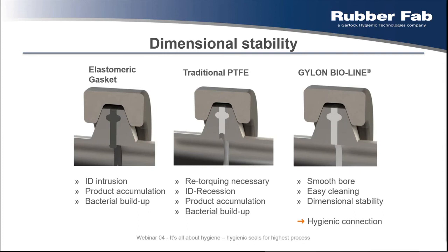I'm not seeing the chat right now, but I think I'm clear on the question, and I would like to answer this briefly because I'm sure this might be a good topic to go into detail further on, maybe at a different time. But let me describe briefly why Bio-PRO Plus, a 100% PTFE gasket, that's correct, has a reduced cold flow compared to a traditional virgin PTFE.